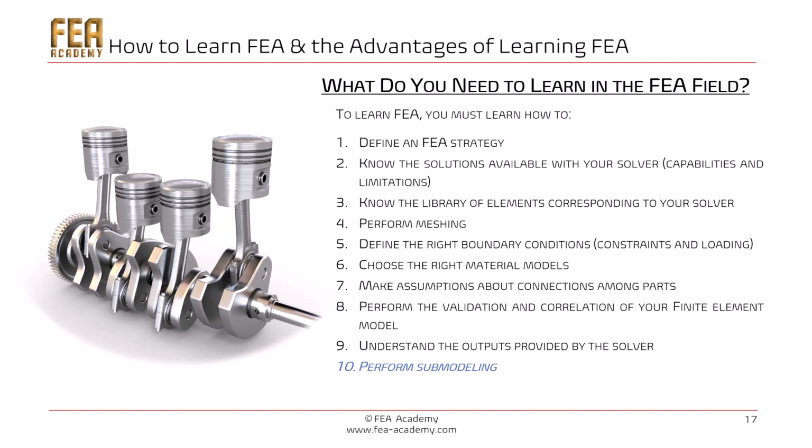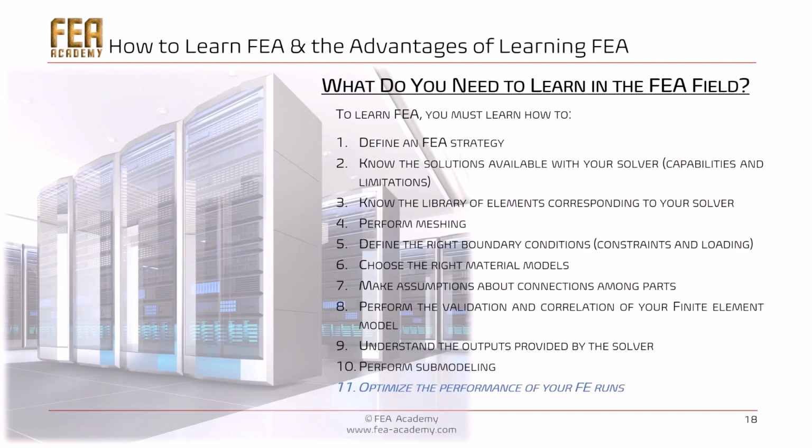You will have to learn how to perform submodeling. You have to learn submodeling because it is a modeling technique which permits to build very detailed analysis in a particular region of a model without the need to refine the whole model. This is a very powerful technique.